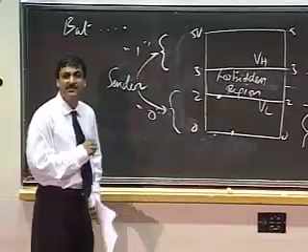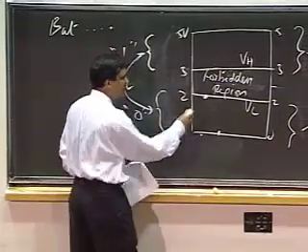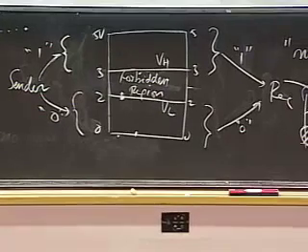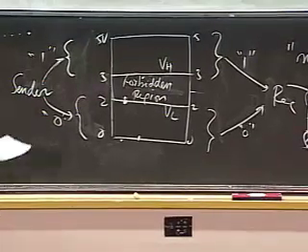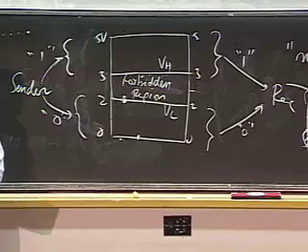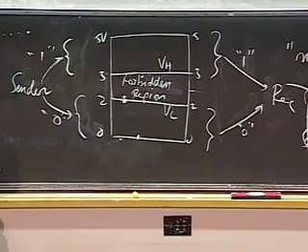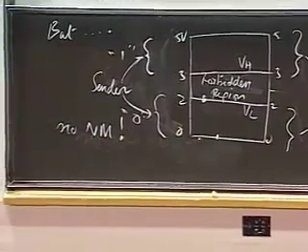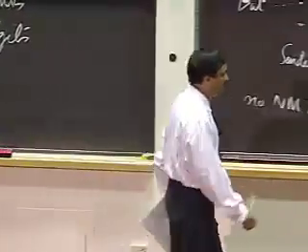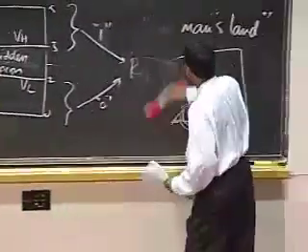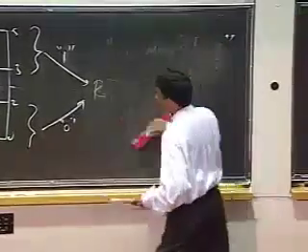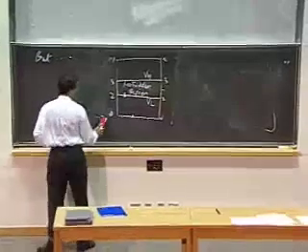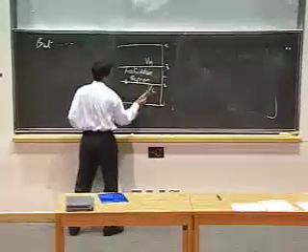This way I can make really cheap parts. But now the problem is that even the smallest amount of noise will bump it into the forbidden region, and therefore this one has a problem. The problem is that this one offers 0 noise margin. There's no margin for noise in this discipline. All right, back to the drawing board, folks. Switch to page 8. Okay, let's get rid of all the stuff and go back to the drawing board.